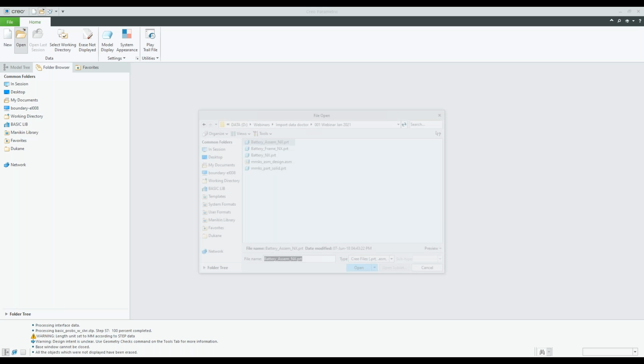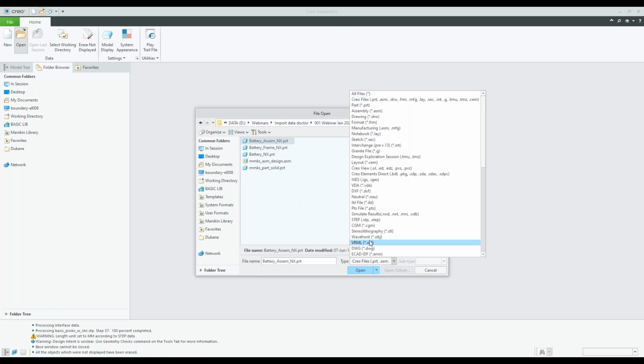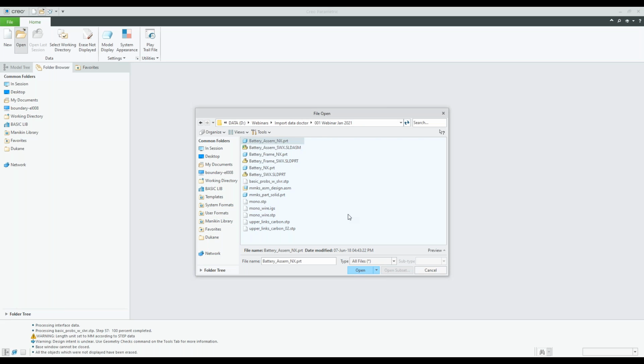So whenever possible, use step files. They are still worked on or developed today. IGES files, things like that, not always that great. If you're requesting data from other customers or from external sources, step file if you can.